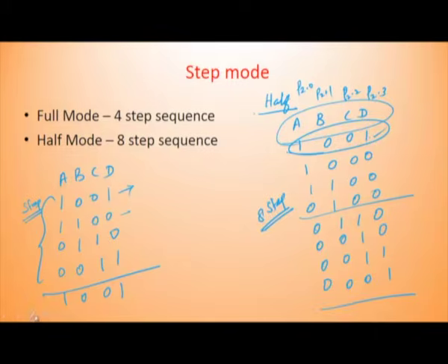So, these 4 signals are connected with the 4 coils. So, how I will write the program: set bit, right, port 2.0, then clear bit port 2.1. For C which is connected to port 2.2, clear port 2.2. Okay.